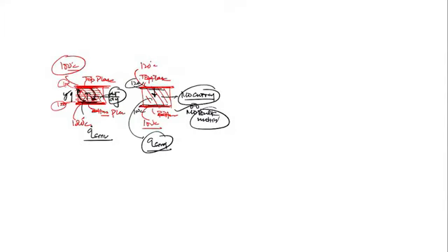So please can you tell me in which case the rate of heat transfer is faster? Same fluid, same thickness. Here it's 1 millimeter thickness. It's also 1 millimeter of thickness here. Temperature difference is also the same, 120 minus 120. Thickness is same. Fluid is same. But still the rate of heat transfer is faster in the convection. Why is it faster? Because of motion in the fluid.